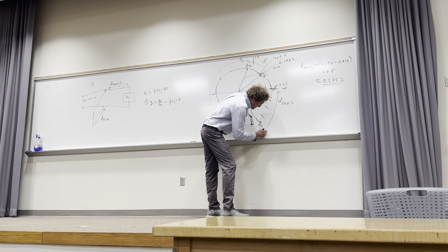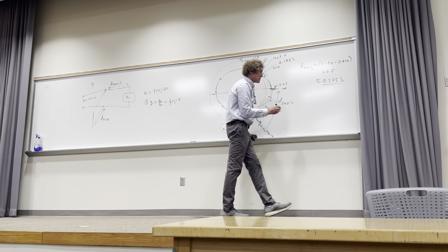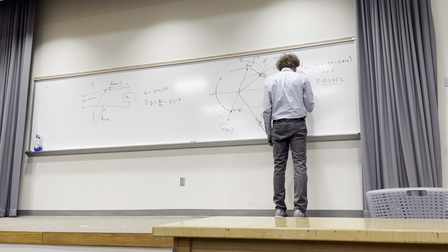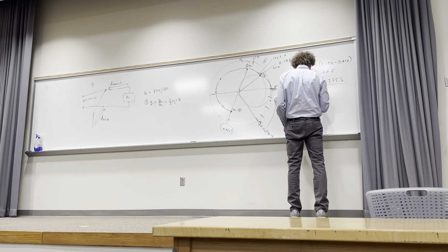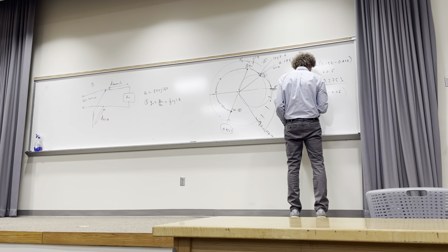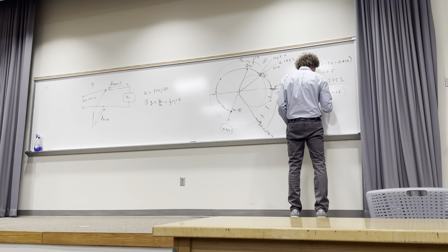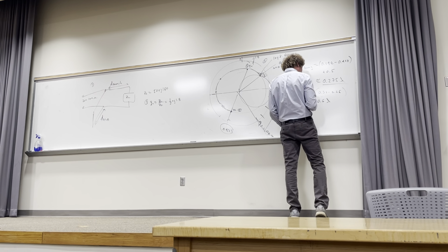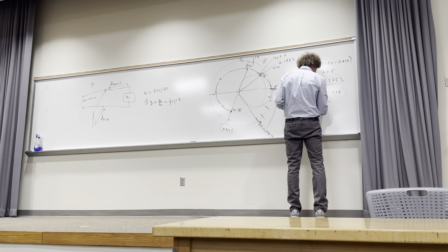So this one here is 0.31, and that's on the wavelengths towards generator, which means now the stub length is going to be 0.31 minus 0.25, and you can call that approximately 0.06 lambda.